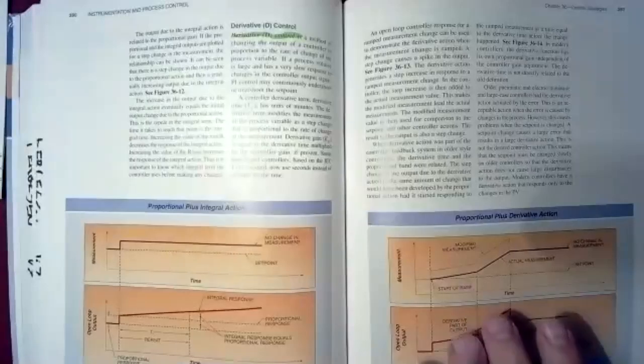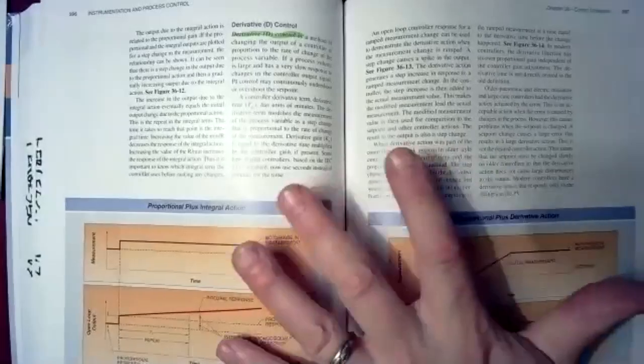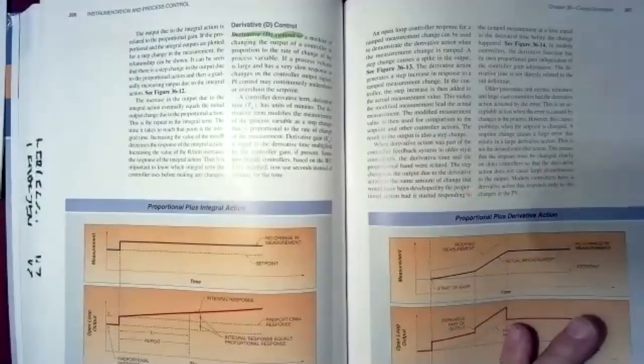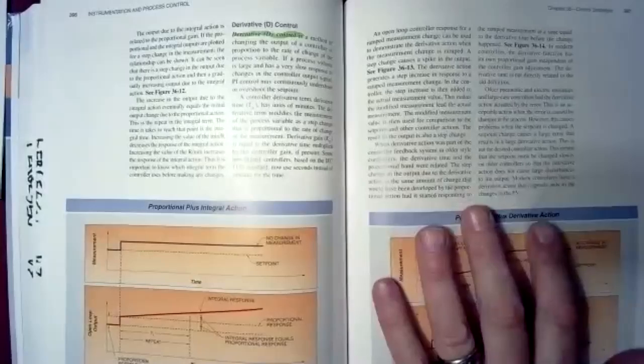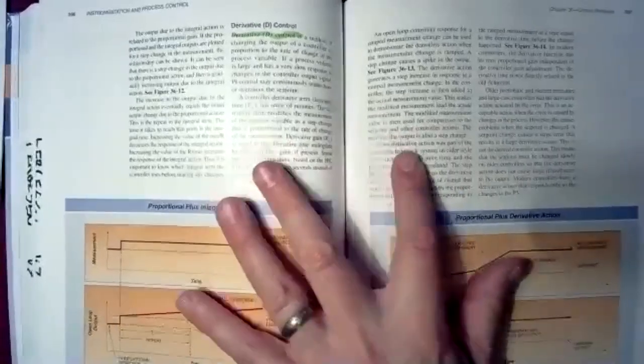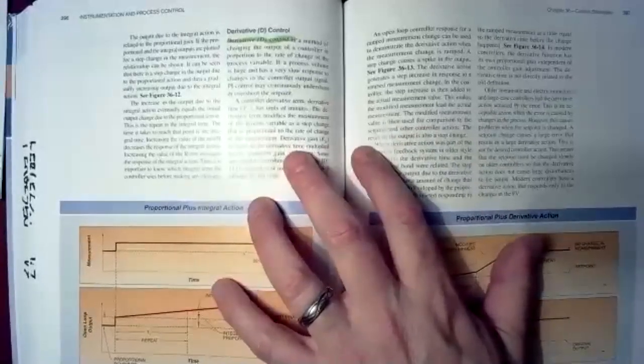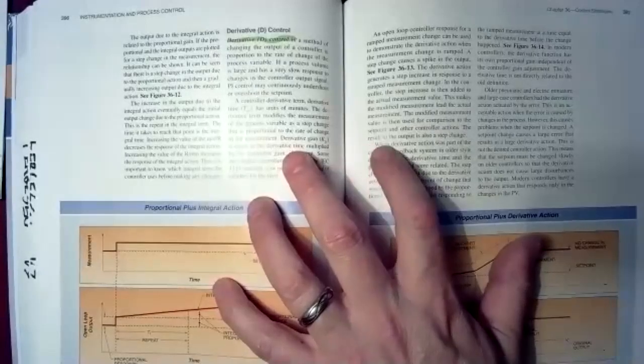And frankly, most modern controllers do PID loops automatically. You don't have to do anything about it. You don't even have to set these parameters yourself. It will be auto tuning. And so the little cheap controller that we used in class is an auto tuning controller, and it doesn't need anybody to set these parameters. It does it for you. The book talks about these parameters just to give you guys a background on how this control works. Derivative control is great for giving you a very accurate target in terms of set point versus actual control level.